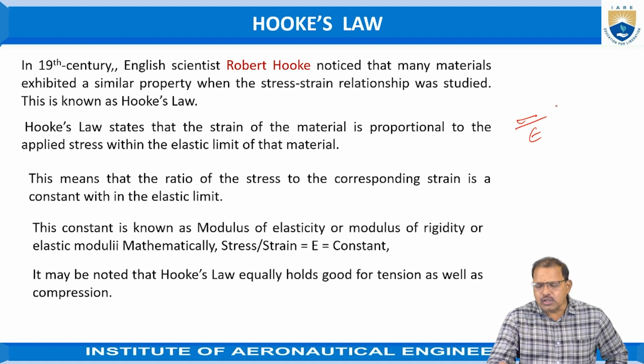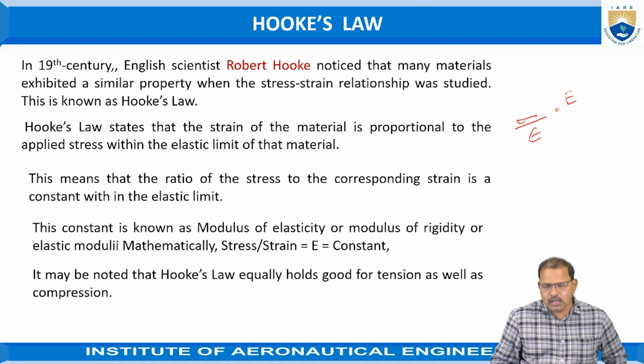So the ratio of stress to strain is constant. This constant is known as Young's modulus. It is a property of the materials, and it varies from one material to another. Hooke's law holds good when the materials undergo tension as well as compression.